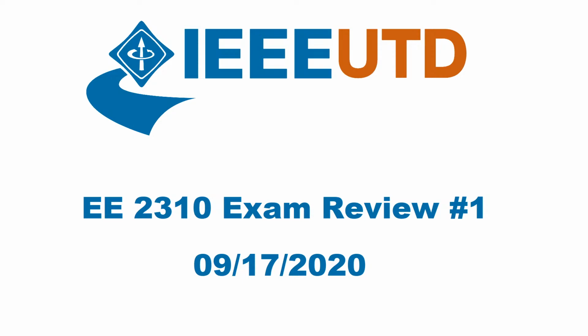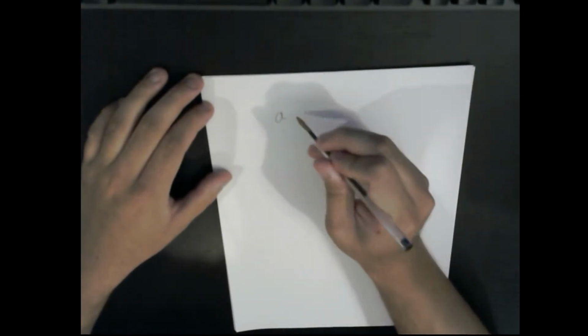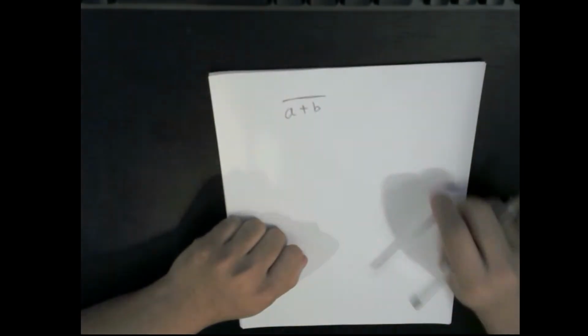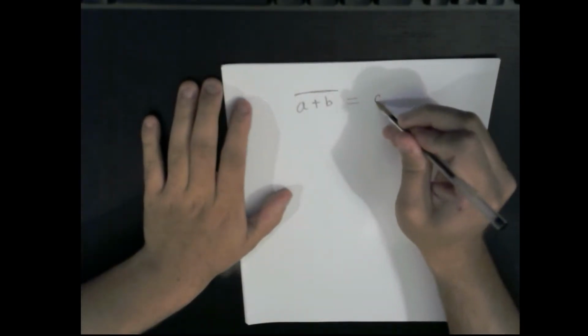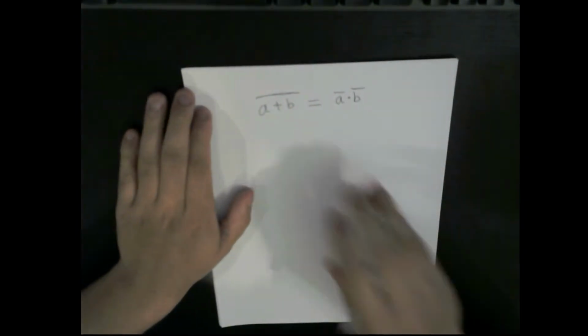All right, gonna move on here. So DeMorgan's Law. This is an important one for when we start talking about converting between NAND logic and NOR logic. So what is DeMorgan's Law? So let's say I have some equation like A plus B with an inversion on top. What DeMorgan's Law says is that these expressions are equivalent. It's saying that A and B with its inputs inverted, these are equivalent expressions.